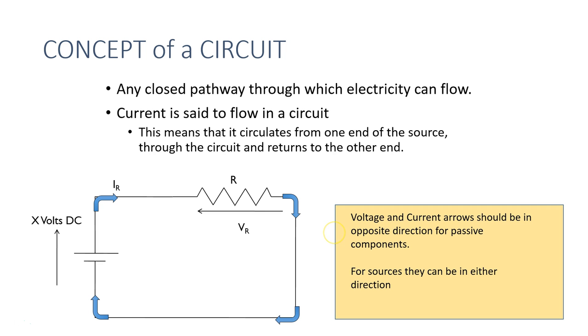So to get into it, what is a circuit? Now if you think of a circuit of any kind, like a racing circuit or even the circuit at the gym, it refers to a closed pathway. You start at one point and you go through something and you get back to the start. And it's the same thing with an electric circuit. In this case you're talking about current, and the current is going through some conductors and some components, resistors, capacitors, inductors, etc., and it is going to eventually come back to the source.